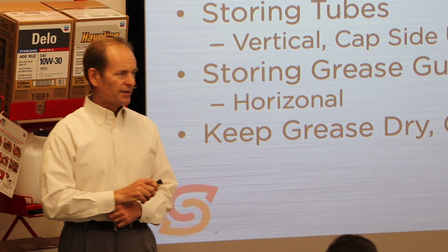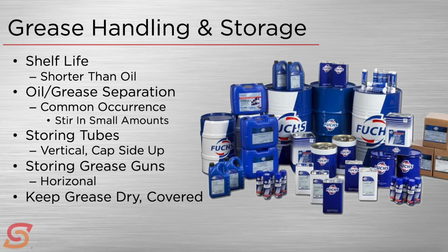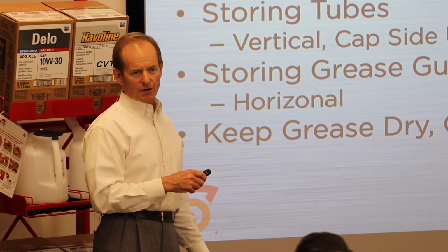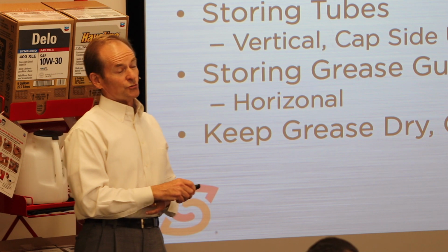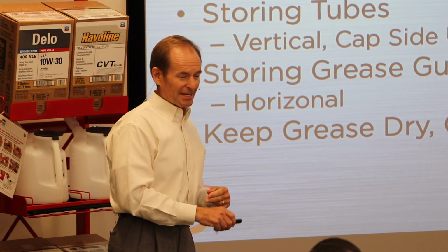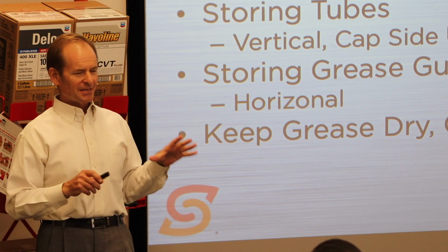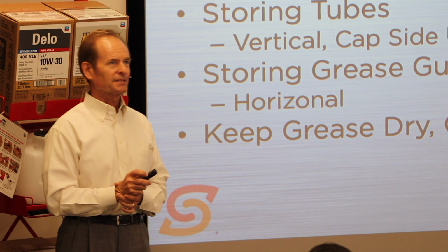Okay, I've probably on more than one occasion gotten a phone call from a guy who says, we had our grease out in the yard yesterday and someone left the lid off when it rained last night. Can we just pour off these 2 inches of water on top and keep using it? Well, you can keep using it. I don't know that that's a real good idea. So keeping it covered, keeping it dry, of course, best storage practices.